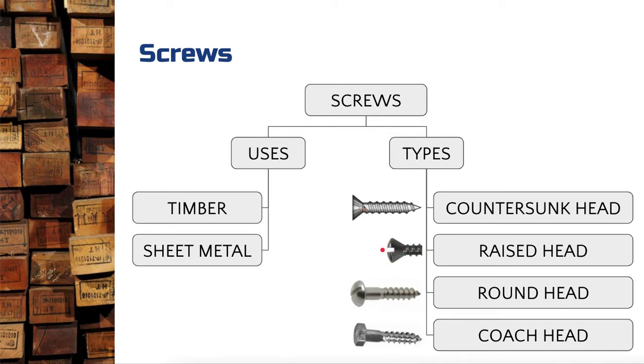There is then the raised head. Now the raised head looks very much like a countersunk, but instead of that nice flat edge, it's got that nice little dome shape there. The benefit there, it has a greater depth of slot that you can work with, okay, because there's more head to work in.